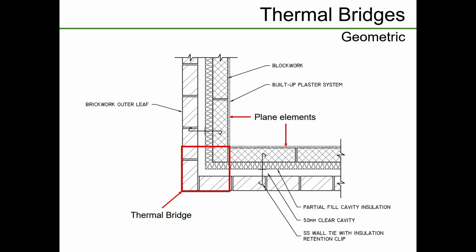And the reason you're getting that is because the internal surface and the external surfaces are different sizes, and because of that you get essentially additional heat loss in this corner even where you've got continuity of insulation. Okay, so you could have this in many different scenarios. You could have it in an exposed floor, say above a porch, maybe if the first floor projects out or so on. So there's loads of different scenarios this could apply.